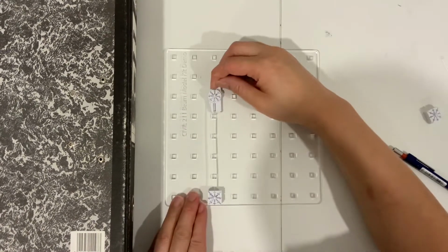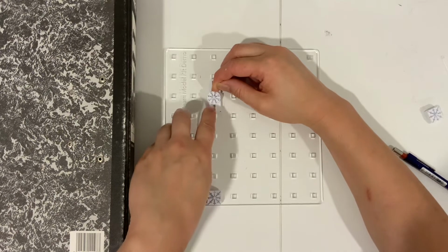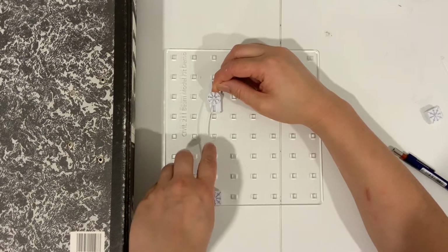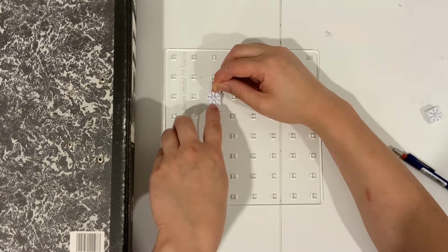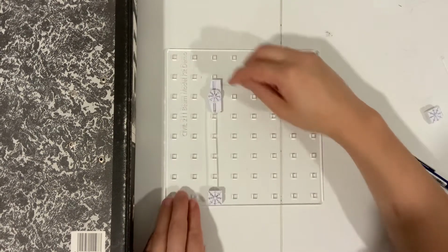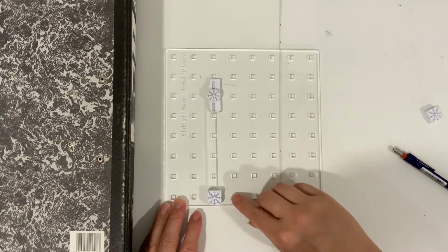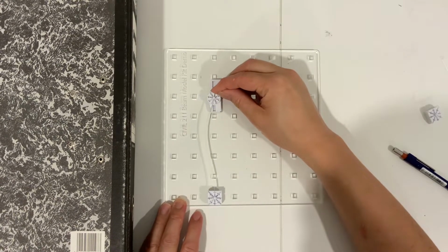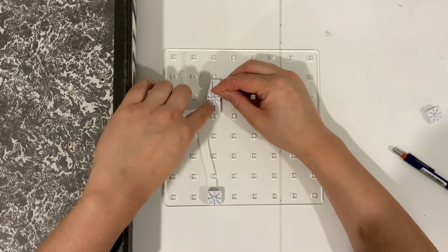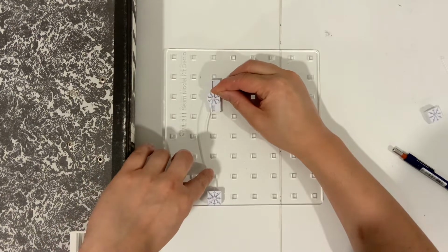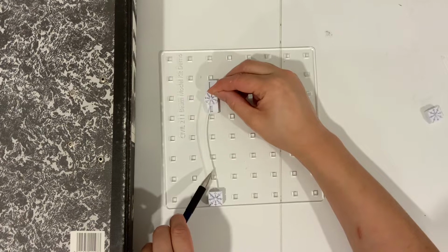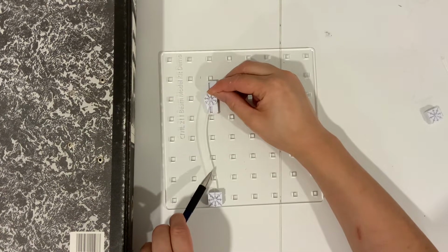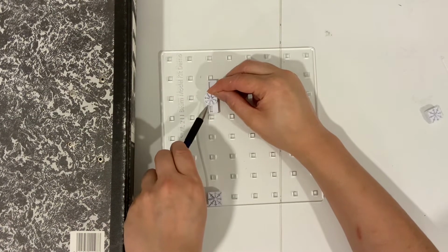So you could sort of deduce that's also a sine function, a sinusoidal function, but the length of the buckle is not from here to here. If we look at the deformed shape here, we could probably see the buckle could be from that point there, or the length of the half sine wave could be from there to there.